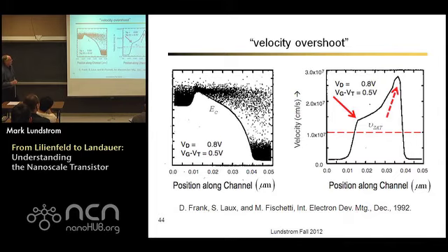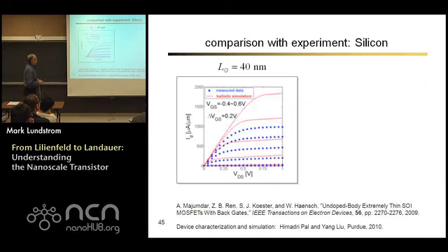Right. Okay, so just very quickly, you look at this and you say, does this have any relevance to modern transistors? So just compute this ballistic theory. Those are the red lines. Compare it with measured characteristics. What you typically find these days in a silicon MOSFET is that the devices operate at about half of the ballistic limit. They give you half of the current that you would get if you had no scattering in the channel and the transmission was 1. That's actually pretty close.